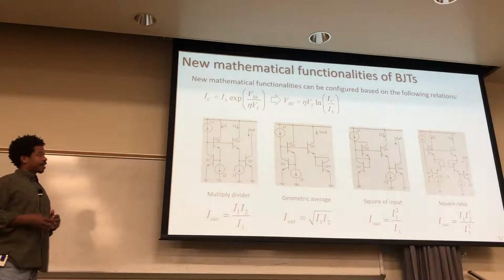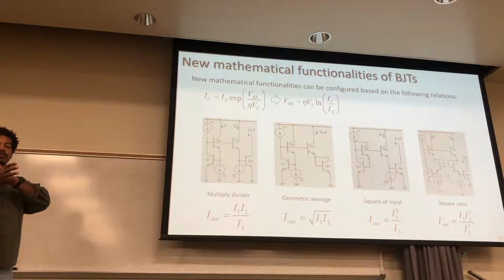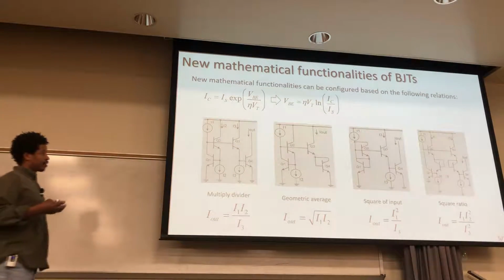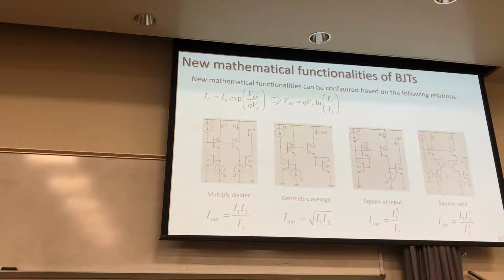When you have changing capacitance, you have current moving onto a capacitor and moving off. That current is proportional to the displacement or the velocity of how the MEMS device is moving. So that's the current, and there are things you can do with that current and feed it back.